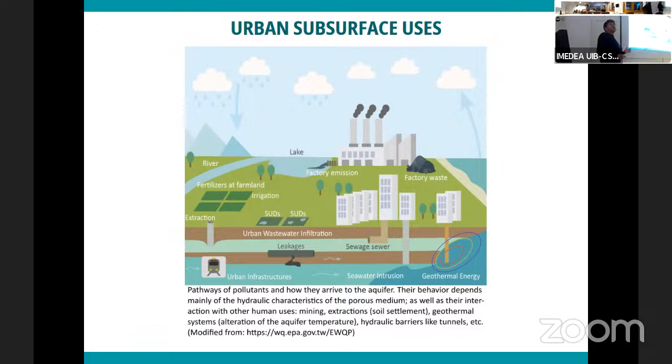The velocity of groundwater is very slow. We work with meters per day. It depends on the geology, whether it's quicker or slower. For instance, here in the Balearic Islands, we have karst, with caves and holes that act like a river, but that is not the common case. In all geological materials, we will find water. The problem is the velocity at which we can extract it.